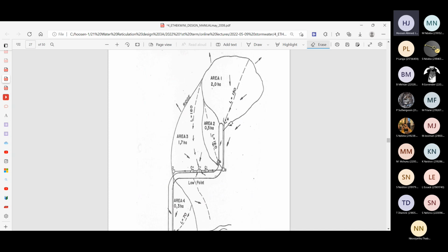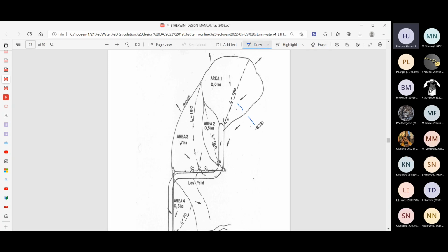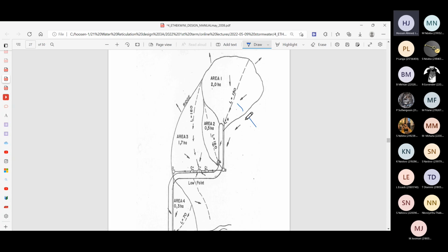So, for example, there might be a hill here, and that divides any rainfall flowing on this hill. Some of it's either going to flow down the hill on the left hand side, or on the right hand side. So that will be your watershed, what we would refer to as a watershed, if you've done geography in school or you've done geology at campus. So you would go about in a map and identify these catchment areas, and that's what's been done over here. So we have four catchment areas.